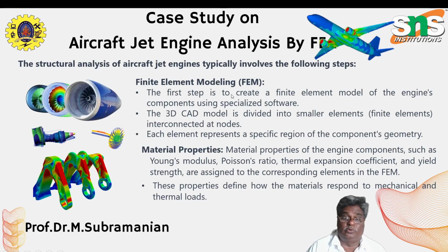The first step is finite element modeling. Create a finite element model of the engine component using specialized CAD software. The 3D CAD model is divided into smaller elements. It's called the discretization approach. The finite elements are interconnected at nodal points. Each element represents a specific region of the component geometry.